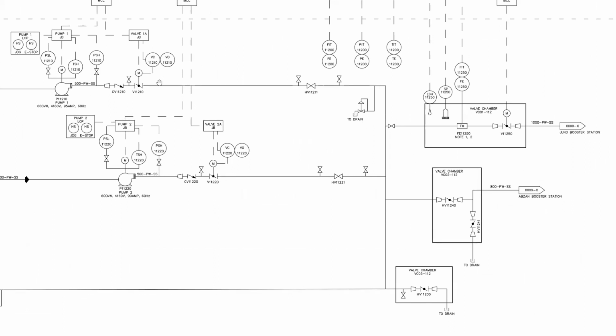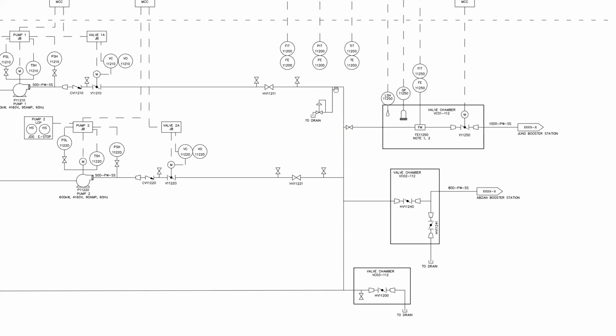We move further down past the two valves. We see some hand valves. These would be upward pointed valves either for taking sample points. Potentially these could be future injection points, or they could be air breaks, vacuum breaks, just drawn incorrectly. What these drawings won't show is if there's an elevation change to try to keep sections of pipe higher or lower than other sections of pipe. We do have a drain here that would indicate this is a low section of the piping system.